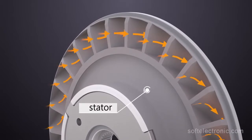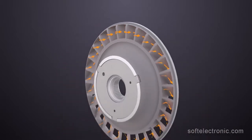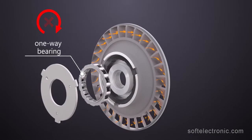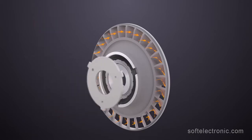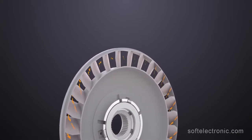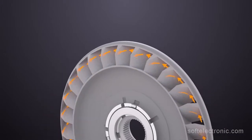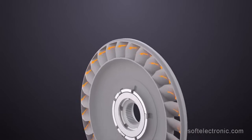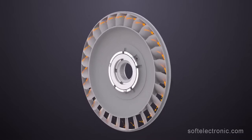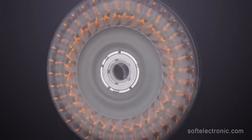At lower speeds, when the fluid passes through the stator, it causes pressure at the front of the blades and forces the stator to move backward to the pump and the turbine. To prevent this movement, the one-way bearing does not allow rotation in this direction. As the speed increases, the fluid velocity increases, and instead of causing pressure at the front of the stator blades, it begins to press the blades in the rear, forcing the stator to rotate in the direction of rotation of the torque converter. The bearing then releases the lockup and the stator starts to rotate in the direction of the pump and the turbine. The operation of the stator contributes significantly to the efficiency and torque increase of the torque converter.